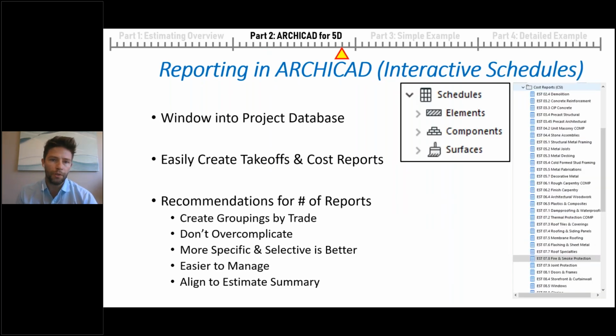Okay, so moving on to reporting within ArchiCAD, we have, of course, interactive schedules, 3 different types: elemental, component-based, as well as surface-based. And these schedules can really be thought of as a window into the project database. It allows us to easily create reports that include quantities, identifications, and other information that's built right into the model elements themselves.